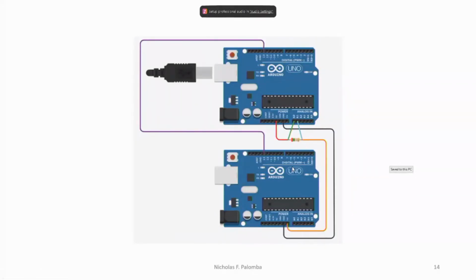As you can see, the top Arduino is supplying 5-volt power to the bottom Arduino through a small resistor, such as 0.25 ohms. The small resistance value must be chosen to ensure that the bottom Arduino receives adequate terminal voltage even when running at full load. So the voltage drop across the resistor can be measured using analog inputs.